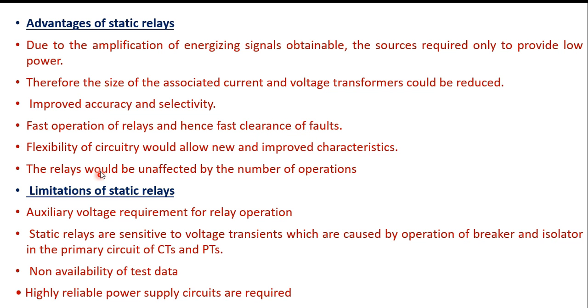And as it is a static relay, we can change the characteristics by changing the resistor or capacitor values in the relay. So there is flexibility of the circuit, and the relay would be unaffected by the number of operations. It will not change its properties with the number of operations.